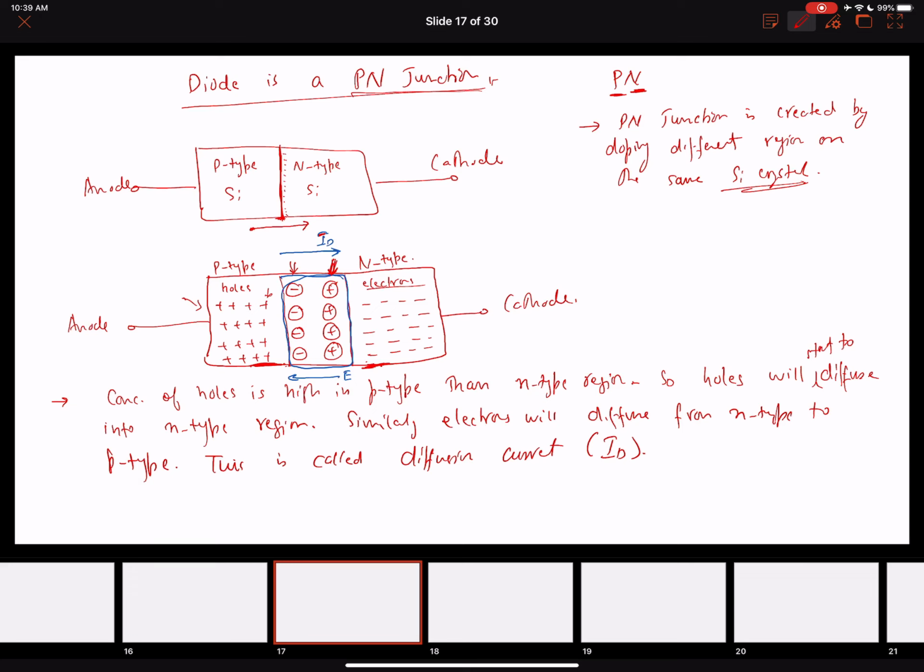A similar process happens to create a negative potential on the other side of the junction. How does that happen? Electrons are moving from the N-type to the P-type. They will recombine and neutralize. More holes will be neutralized near the vicinity of the junction, and we are left with these extra electrons. That is why at the barrier we get this negative charge here. Now, if we look closely at this region, this is a depletion region. This is also known as a barrier potential.